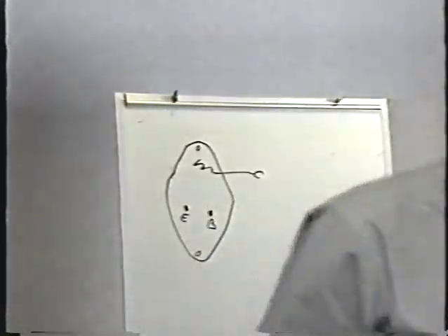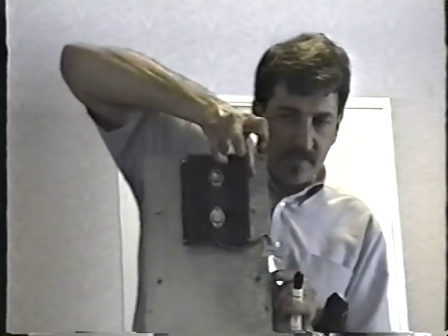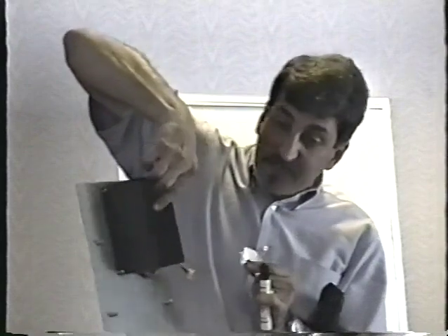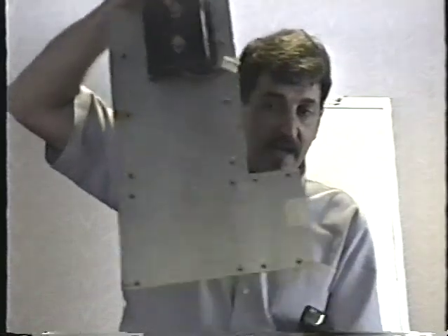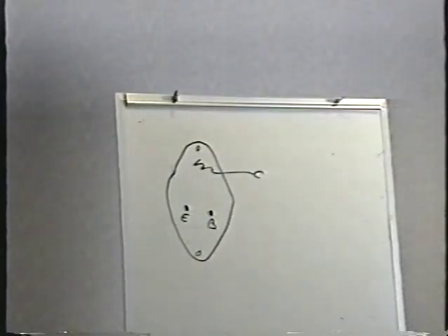Well, I can show you a heat sink here. Here's a couple of them, in fact. If you look on this metal thing here, this finned aluminum thing is called a heat sink. Transistors don't like to run hot, and that's why they're mounted on this heat sink. Whenever you see transistors mounted on heat sinks, you'll see these insulators mounted behind them. You don't mess these up. I'm just going to pass them around so you can look at them. I only have 4 of them here, so be careful with them. These are made out of mica. They're fairly delicate, so don't screw them up.